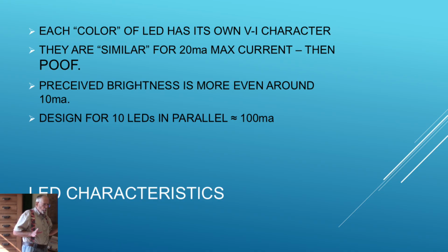So in the design, what I said was, that's okay. That's going to be my brightest point. So I designed everything for 10 milliamps through each one of the LEDs. So the design for each channel is 10 LEDs in parallel, which is 100 milliamps. So it's 100 milliamps per channel.